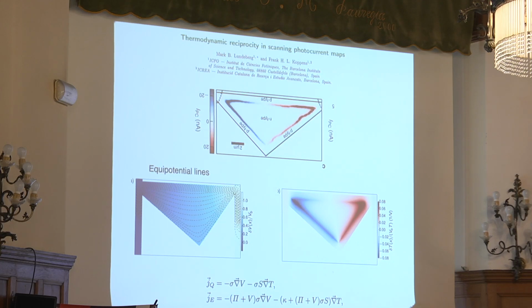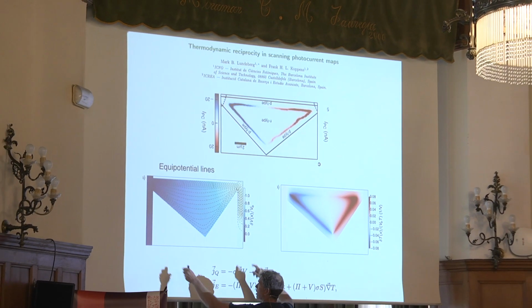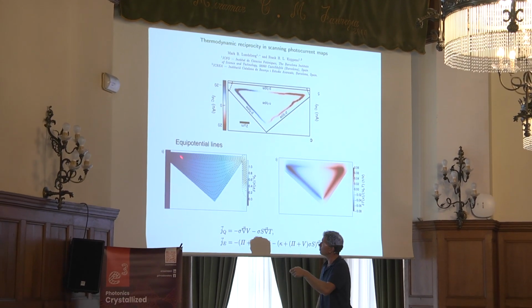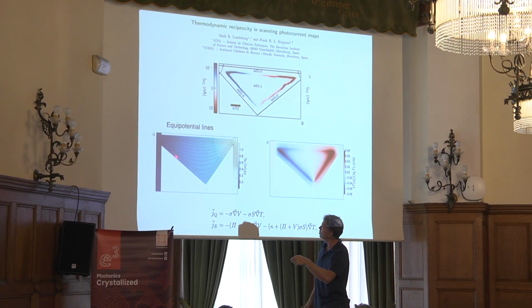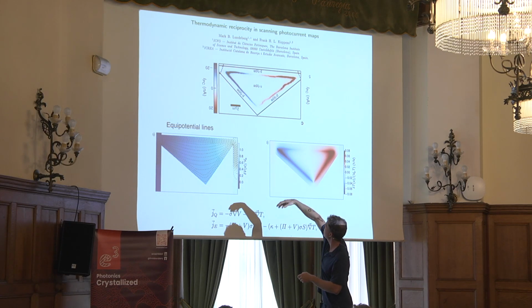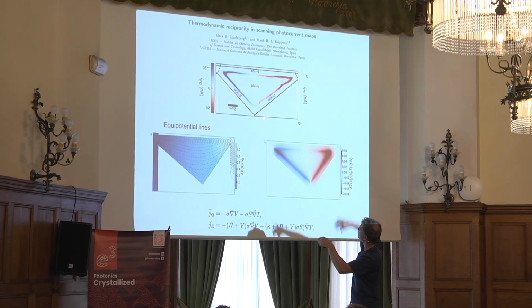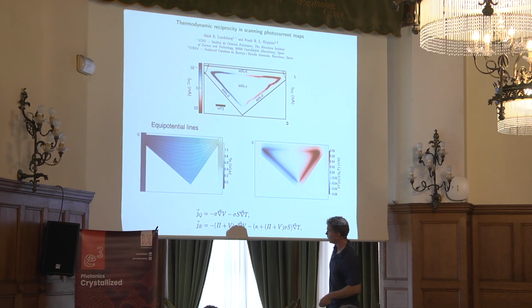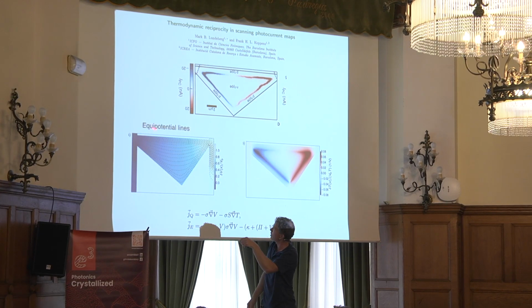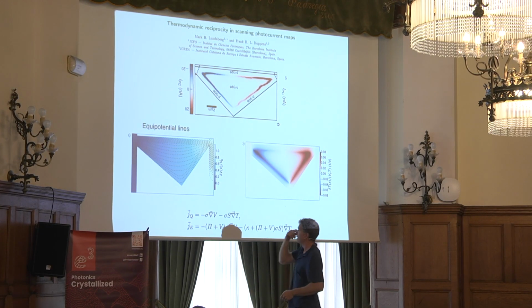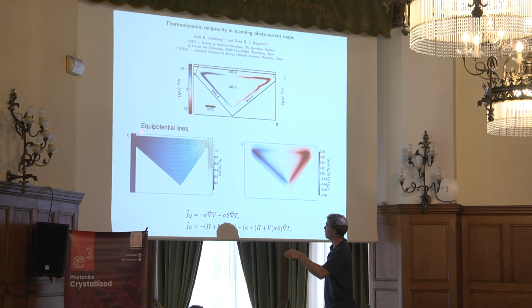So what you do is that you basically calculate first equipotential lines. You apply a bias between source and drain, and then look at the voltage distribution, or you can actually see these lines of how currents would flow. So now I am simulating this system, which I showed you the data of before. I just flipped it upside down and showed this data, where there's a bit of doping near the edge. So the current is actually going to flow a bit more near the edge than in the bulk, okay? And so these are the equipotential lines.